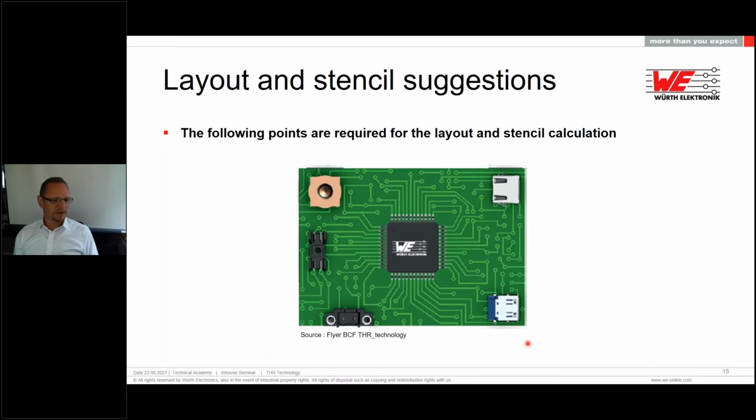And one remark from my side: in the very beginning when THR came up, we saw that some manufacturers just changed the plastic materials inside of a component, and then they confirmed it's a THR component, which was not the case, because the pins were much too long, and some had holding parts, maybe clamps, and you can't force the pick and place machine to push the component into your PCB during assembly, or only very limitedly, so this would not work. So take care about that.